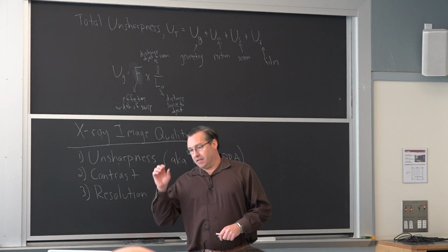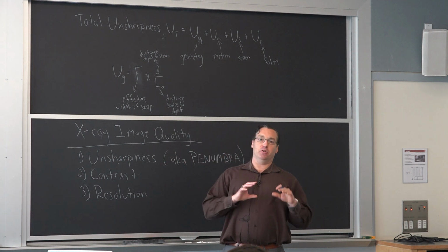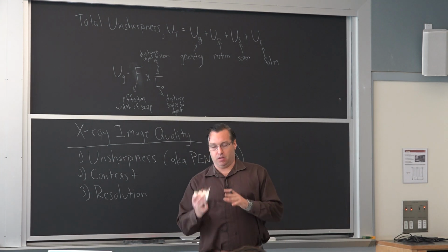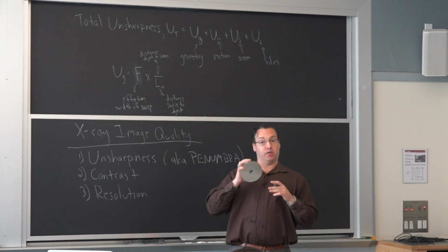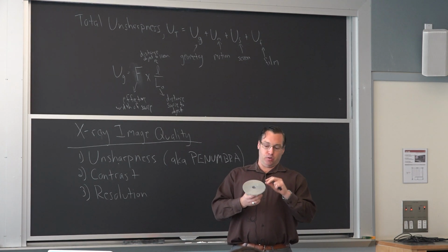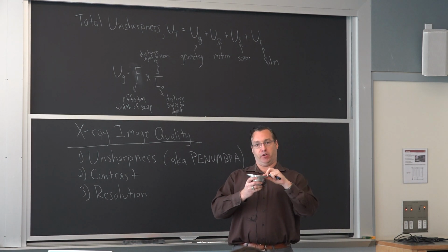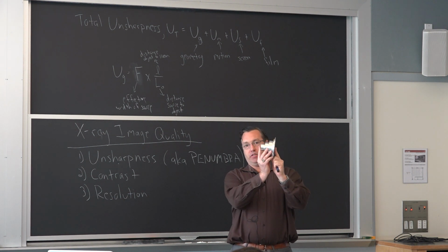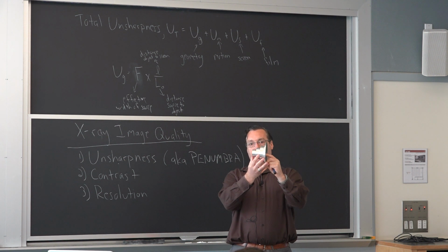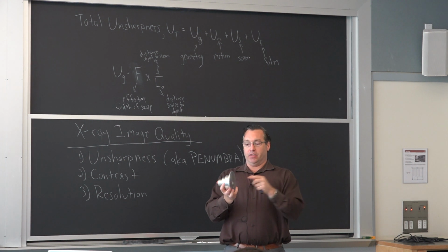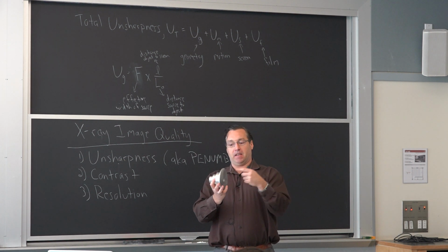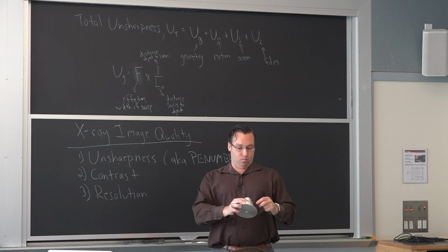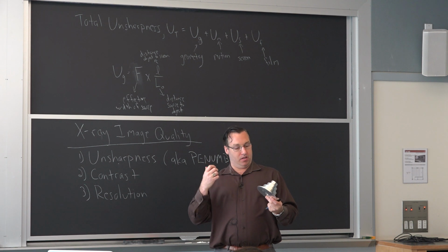The example I'll use is for computed tomography. If I was looking at a 6000 series aluminum, I would use either a 1 millimeter or 2 millimeter screen. The choice of the screen depends on the longest dimension. This is the limiting factor, because in the longest dimension you have to have the X-rays fully penetrate and then come back. That's one of the things you'll see in the images.